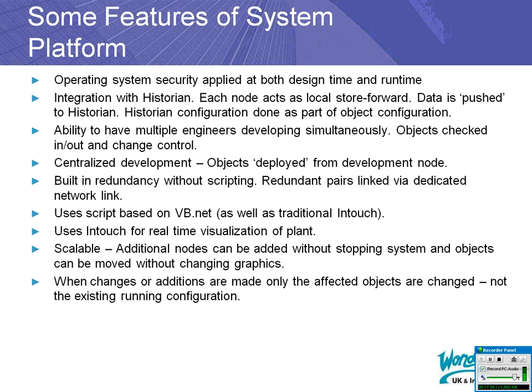A big thing is, when you are making a change to a System Platform application, for example, adding a new valve, the change is only for the object that you're deploying. The rest of the system carries on running normally. Now, if you think about a SCADA application, when you need to make a change, you have to stop the SCADA application, load a new application, and then restart that new application. And meanwhile, you're hoping that you haven't changed anything that was in there and running the way you wanted it. You don't have that issue with System Platform.